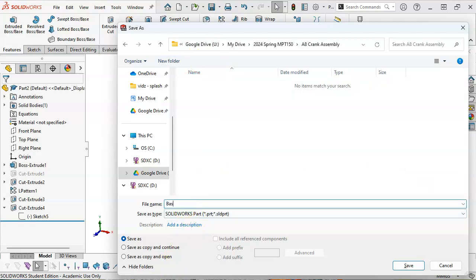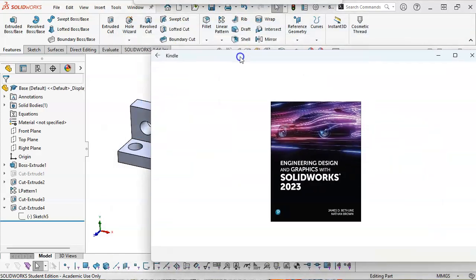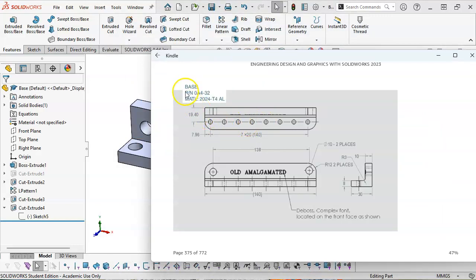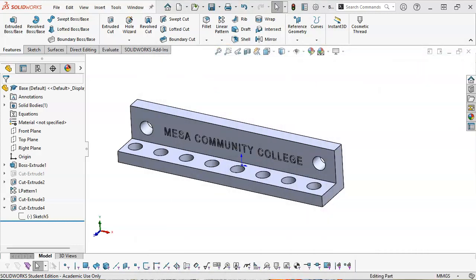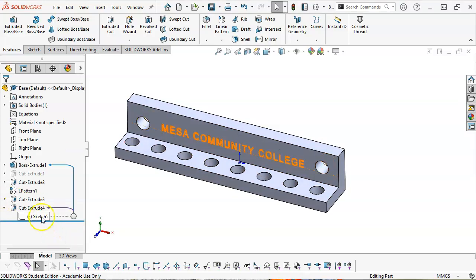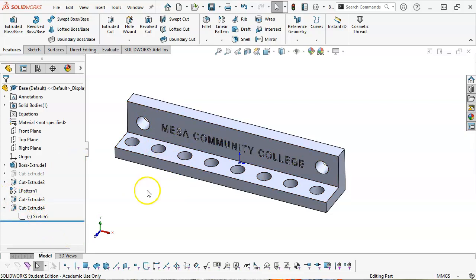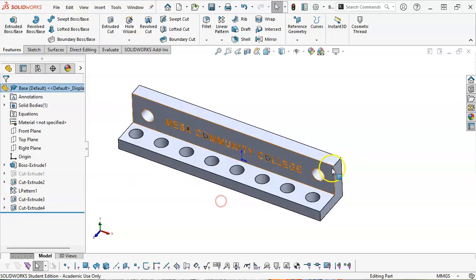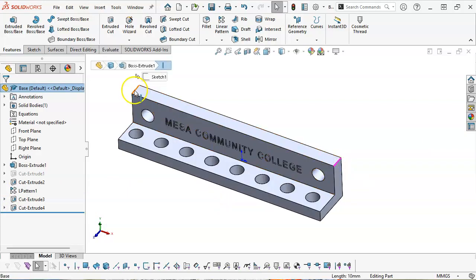All right, so we're going to go through a little bit more on our geometry, but we have a base for the title, our part number, and a material of 2024 aluminum. Not a very common aluminum, so we'll also talk about material selection and going through some of those choices. All right, so it's okay that that's underdefined. The curve is pretty much driving the position, but text has a tendency to not go fully defined.